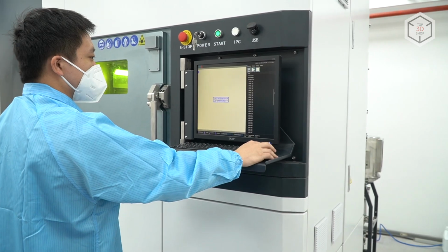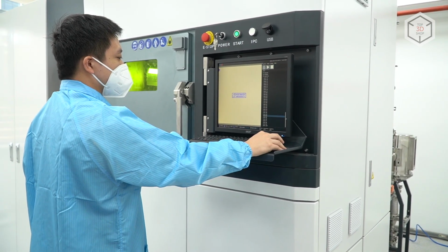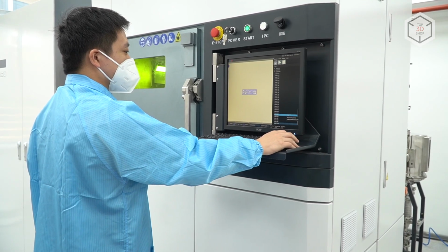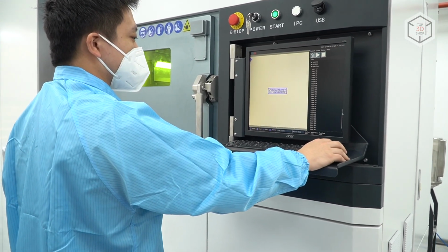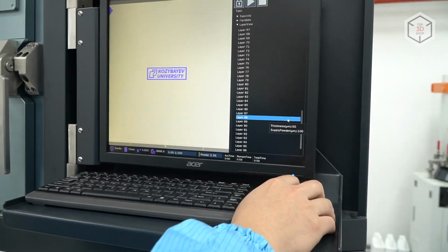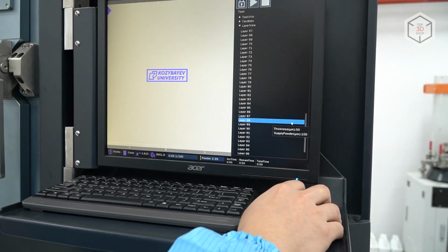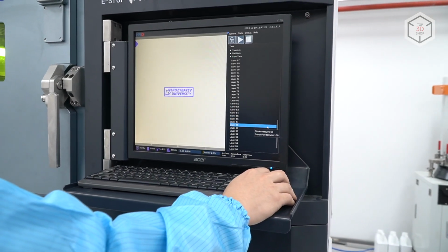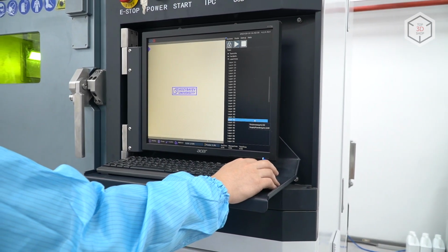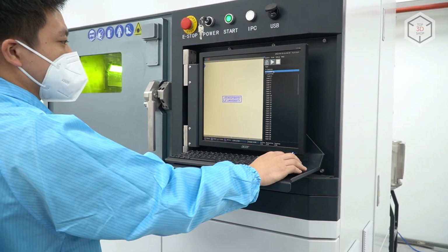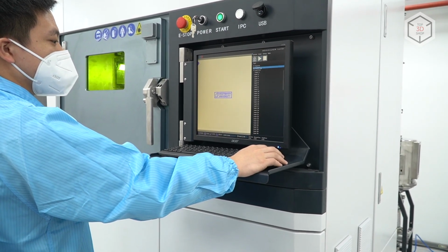In this particular case, the thickness is set to 50 microns and the supply of powder is 100 microns. If you want to change the supply of powder at a particular stage, for example, if the build was large at the beginning and became thinner at the top, we can change the supply of powder from 100 microns to 50 microns in order to make our use of powder more efficient.